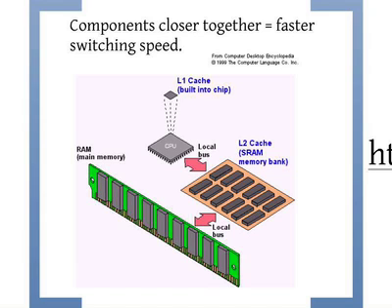If you think about it, the example is actually here. You have a CPU and you have some bus, which is just a channel of communication, which connects to some memory bank. This communication channel turned out to be the bottleneck, and that was probably about 10 years ago. To reduce that bottleneck, people took this memory and put it on the chip itself, so you physically made them closer together.